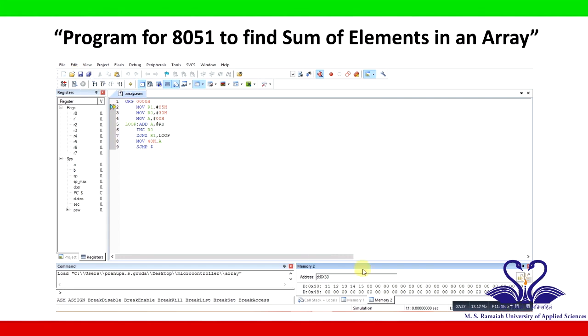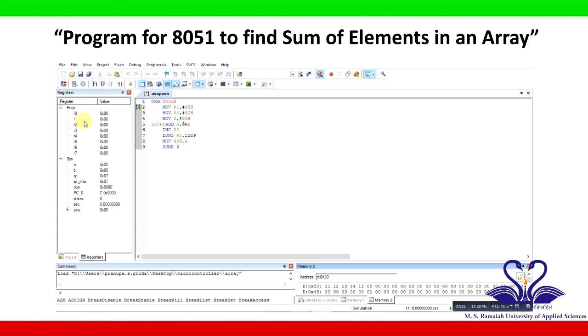So let us start executing this program step by step. As and when these instructions get executed, you can see how the values are going to move into the registers. So now click on step 1 line. You can see this line is being executed, which means MOV R1, #05H. So #05 is the immediate data which is moved to R1 register. So R1 is loaded with 05.